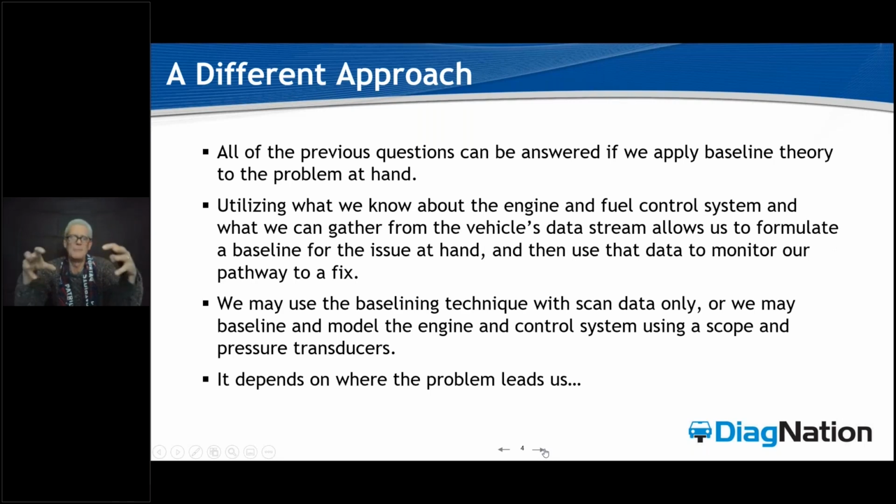For example, the mass airflow sensor acceptable range is 3.0 grams per second up to 15 grams per second at wide open throttle. Well, if you look at those sensor ranges during any diagnostic, never mind just carbon or a problem being caused by carbon, that's significant, okay?